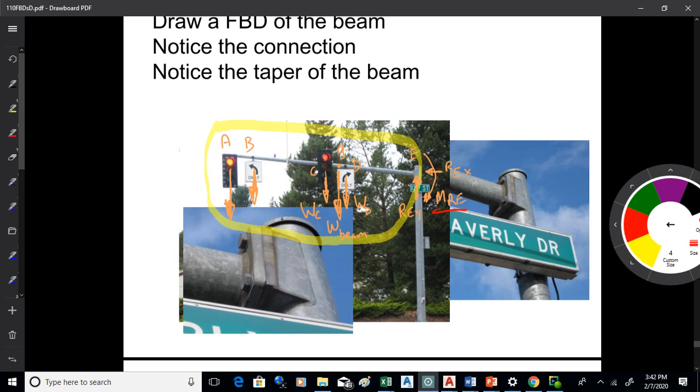Y'all doing all right with that? Okay. We want to get these right because you can't start calculating until you get a decent free body diagram that's correct. On the moment being clockwise, doesn't the weight rotate everything counterclockwise? Yeah, it would, and the moment's going to have to resist that. The resistance. Yeah. So it's opposite; that's the reaction.